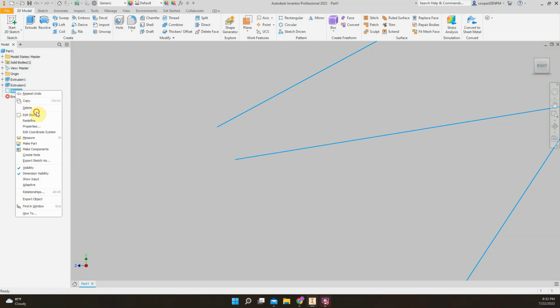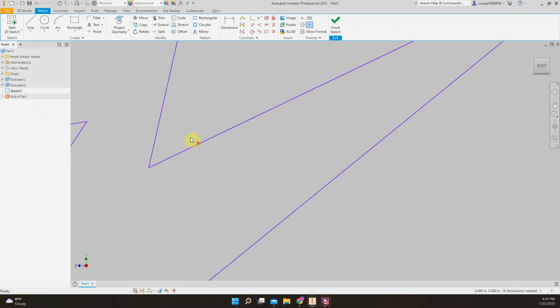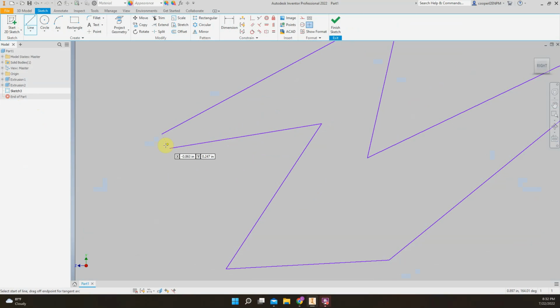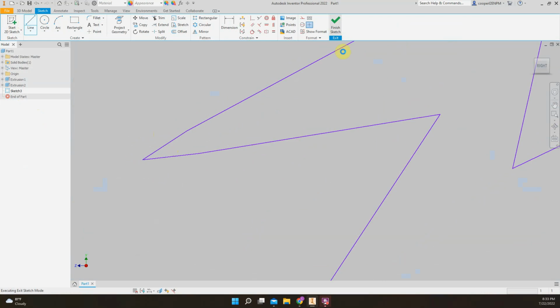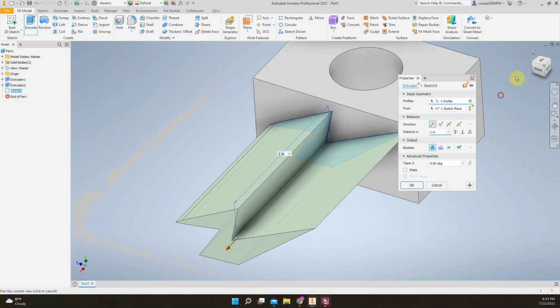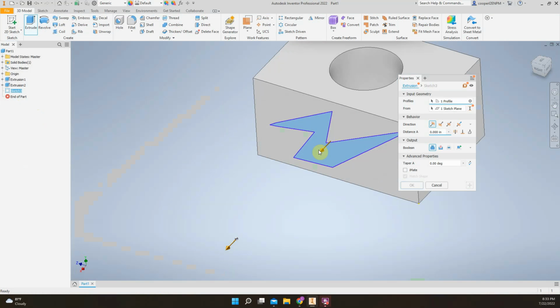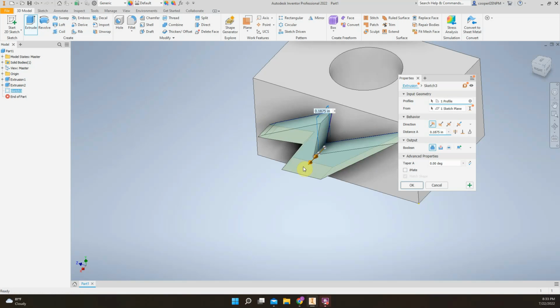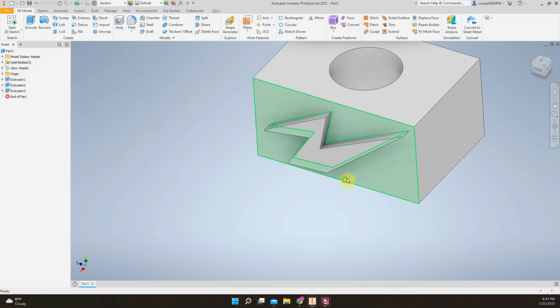You have to make sure that you're using the green snappy points to know you're on the end of that line. So let's go down there. See, I almost got tricked, but there's the green snap. Boom. Finish the sketch. E for extrude. Again, you can rotate around this. That's important. Maybe I only want it out a little bit. You can use this if you're more comfortable, but if you need precise numbers, you need to type them. If I wanted 0.06, I'm not going to get that using this. So I would type in here 0.06 and hit OK.